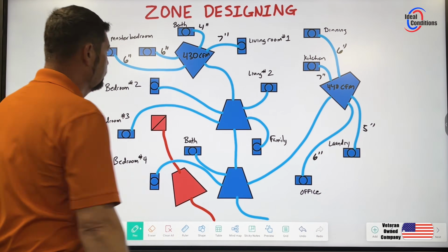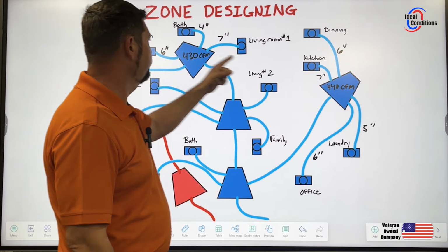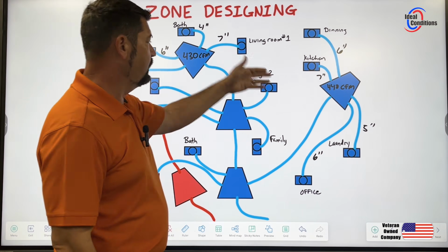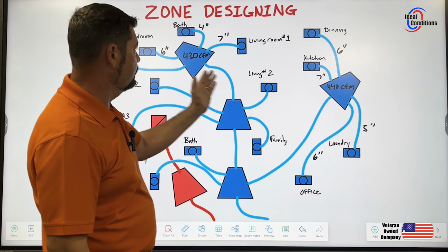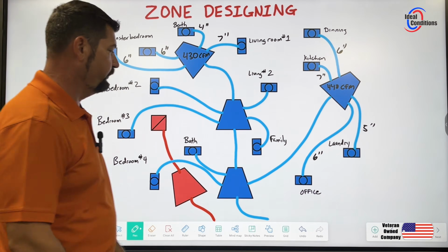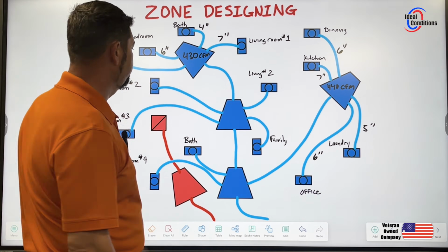Okay. All right. So far, I hope our equipment is at least 2 tons, 2 to 2.5 tons, because we have 870 CFMs. There's 400 CFMs per ton nominal. All right, let's go ahead and get into this third box here.